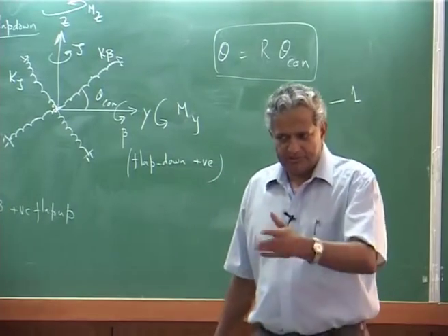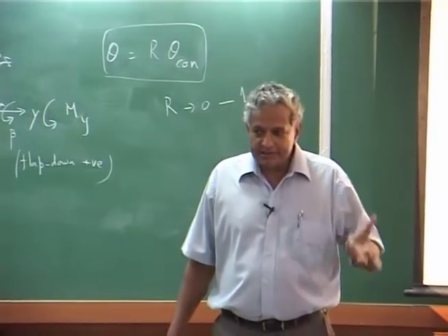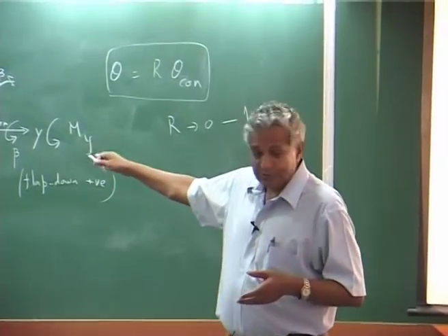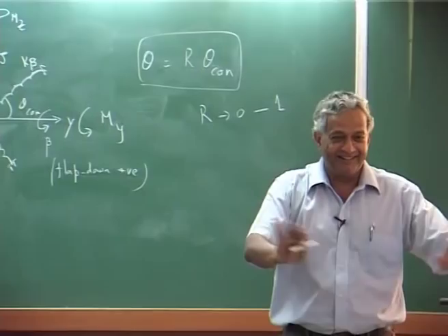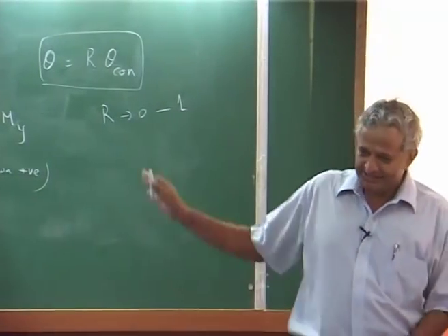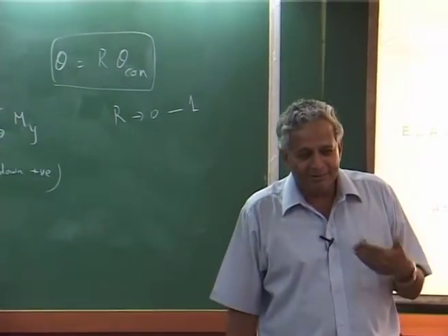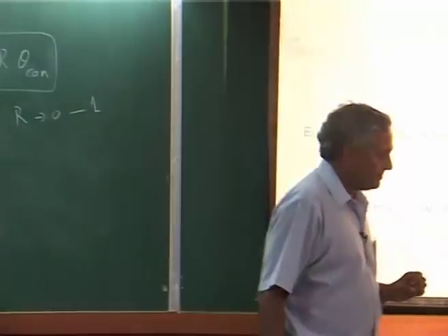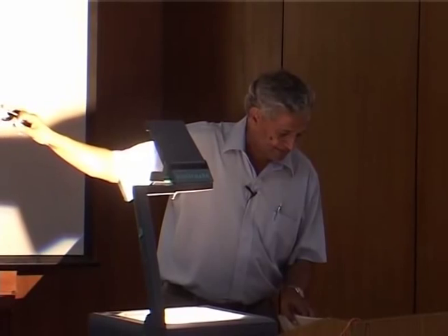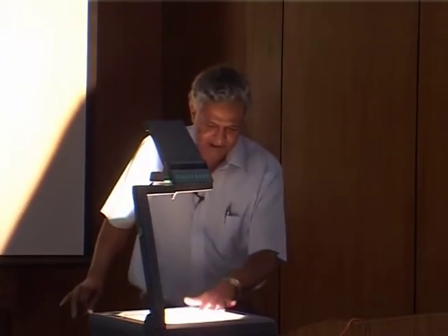And all these things started from the 70s. People tried to understand what is really going on in the flap lag. Those days it was a rigid blade with this type of spring assembly only. In all research papers, if you look, even in the 80s, yes. But now elastic blade models have come, okay. Now I will show that is the matched stiffness configuration which can eliminate the structural flap lag coupling, okay.